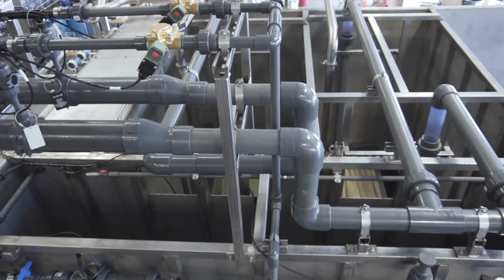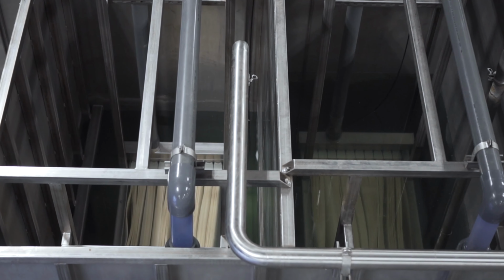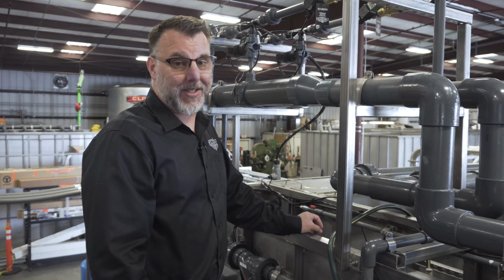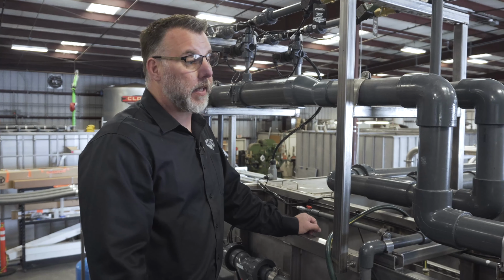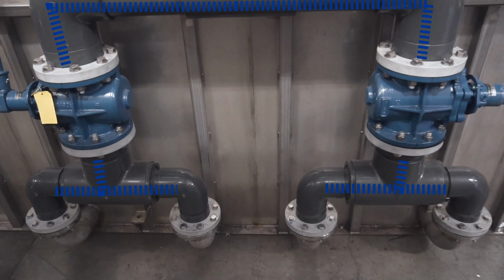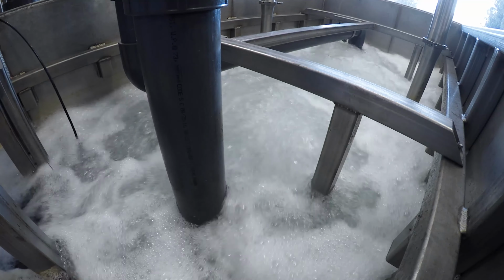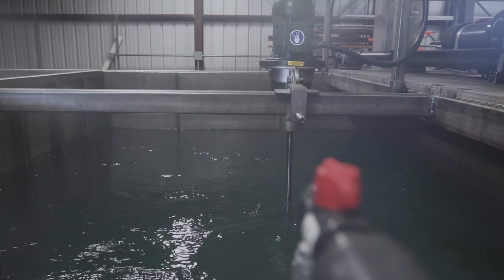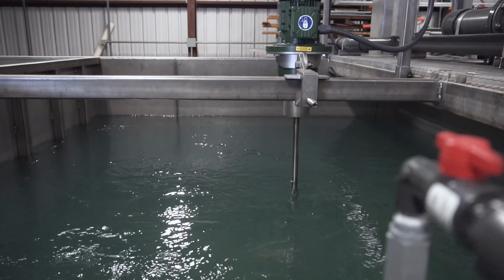This Mempac M50 is supplied with completely redundant membrane cassettes. Each cassette has a dedicated blower, permeate pump, and sensory equipment. Activated sludge is pumped to each cassette chamber where it upflows through the cassette at approximately 5 times the average daily flow. Permeate discharges through the membranes. Excess flow is returned to the anoxic process.